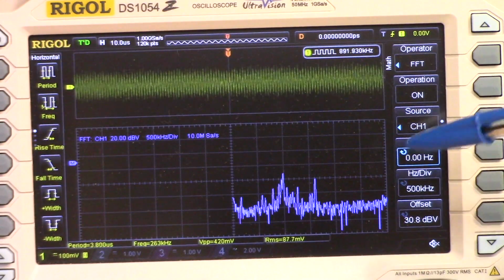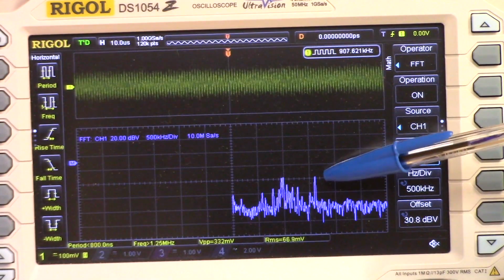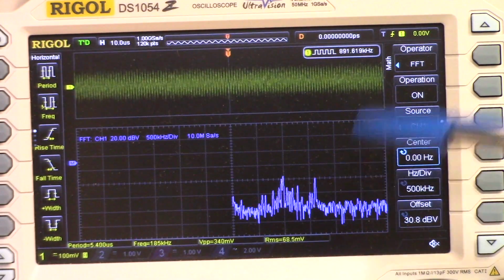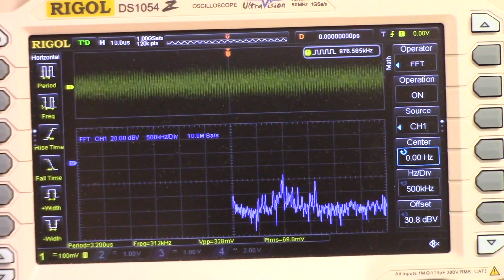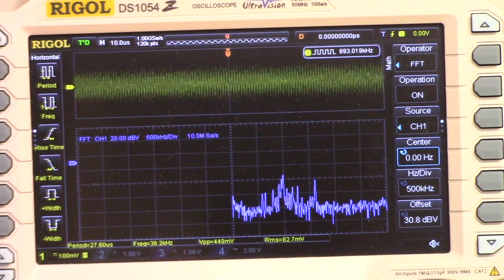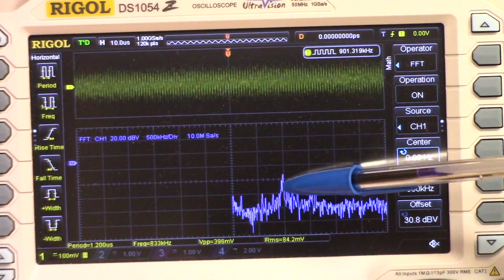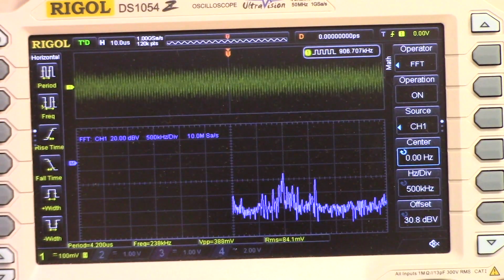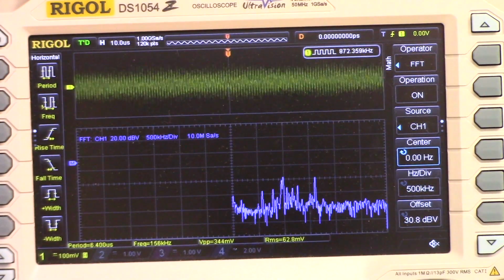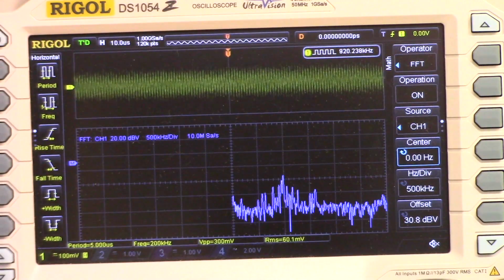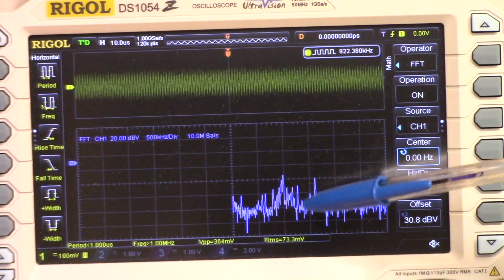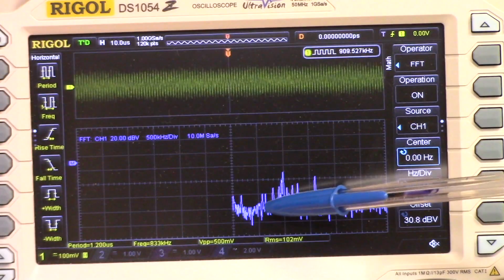So you can see that in my area we've got a very strong signal at 1.6 megahertz. In fact, that is true. You can tune that in my location. We've got something at just less than 1 megahertz, and in fact there's a signal at 980 kilohertz, so that's what that is. And then there's some other signals that we're going to be very interested in today.